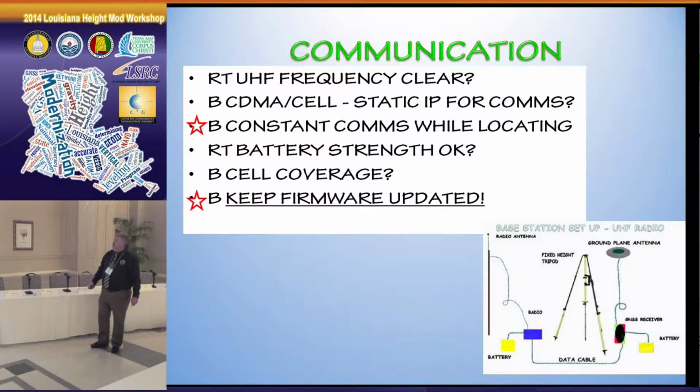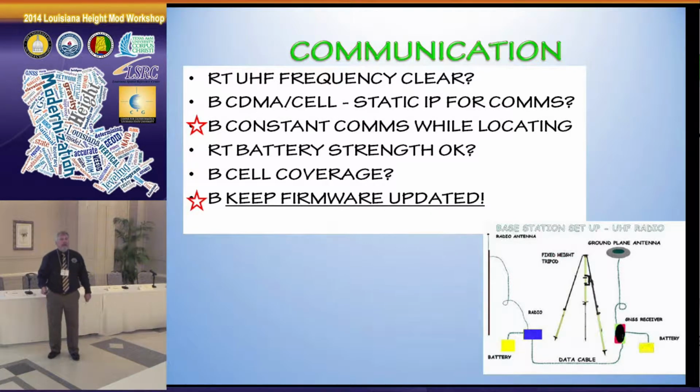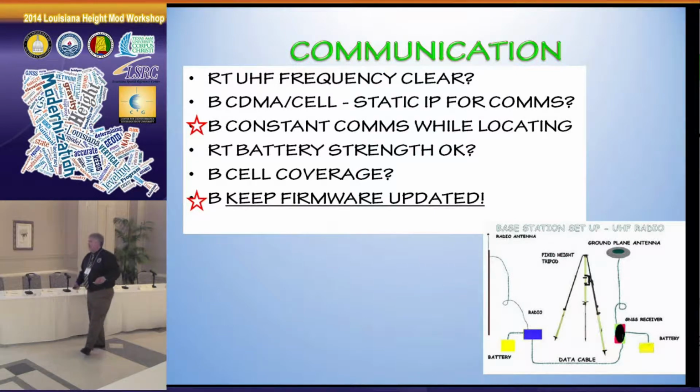Frequencies in real-time single base, you have to make sure they're clear or you're going to get walked on by voice. Voice takes precedence over data. When the radio frequency overlaps or there's a harmonic or something like that, truckers on the interstate, if they're near their same frequency, they can walk over your data. Wait for and get a scanner for a clear channel. Of course, as soon as you go 5 miles away, that'll be busy again, but that's the way it goes.